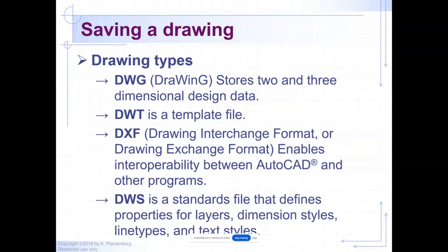All right, then we have things called DXF files. What's that used for? Well, in Machine Shop, I can send a DXF file to those guys, and that will create 2D points inside their MasterCam program that they can pull up and turn into a machinable part, or a machinable program that they can run and create a part that way.